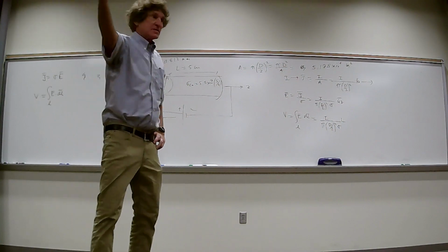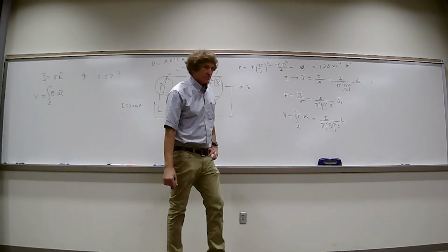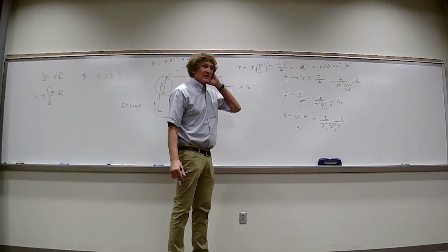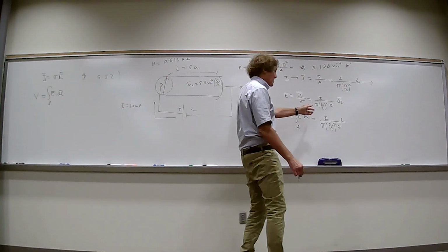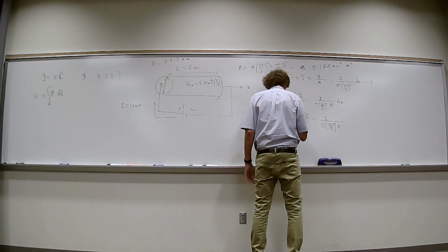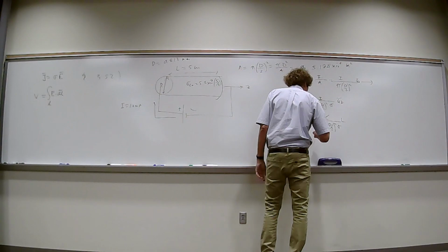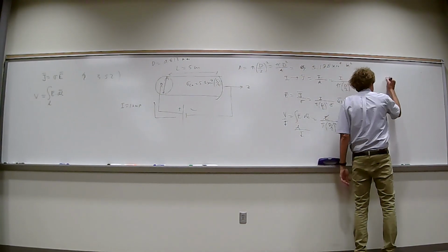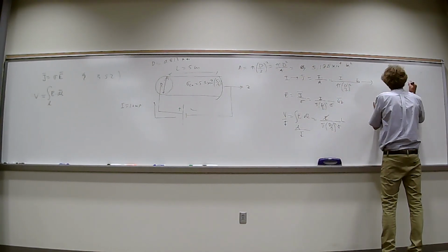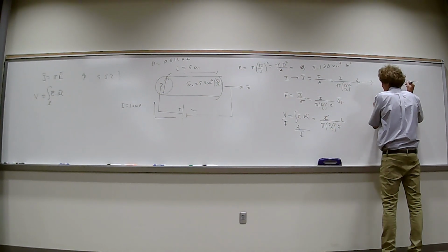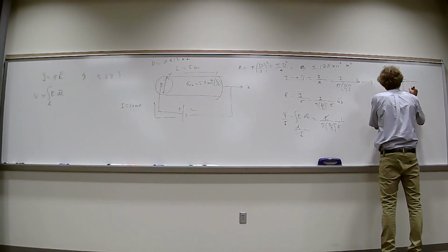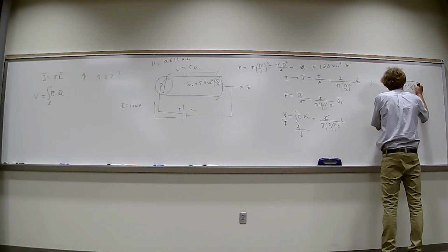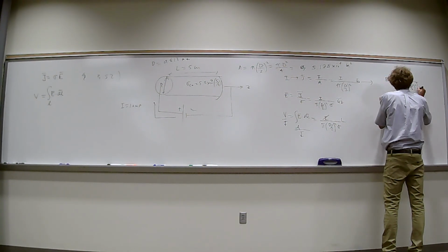All right, finally, the resistance. Always think Ohm's law. V equals I times R. Therefore, if we divide V by I, we get R. And the resistance is simply equal to, it's always proportional to L, it's inversely proportional to sigma, and it's inversely proportional to the cross-sectional area. So that's pi d over 2 squared, right? And that's going to be the resistance.